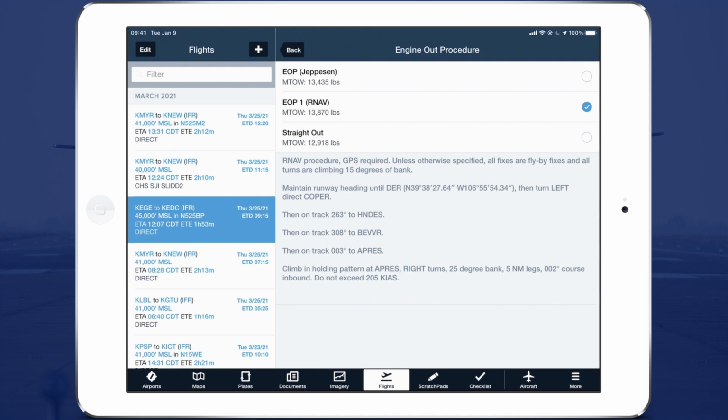And thinking back to some of the other procedures that we have designed, some of these procedures only follow the SID for maybe the first portion of that SID, and then we kind of veer off of the SID because we're targeting lower terrain where the SID takes you over higher terrain. I remember there was a case in Phoenix, I believe, where that made sense to depart the SID. So without having to think about these additional complexities, it does make sense. Can I just maintain runway heading, keep flying straight, focus on maintaining V2 to my level off altitude, and immediately the flyability has become so much easier. So that makes a lot of sense.